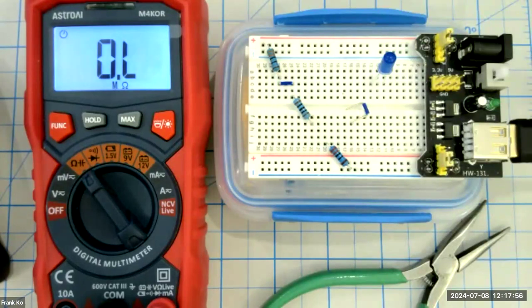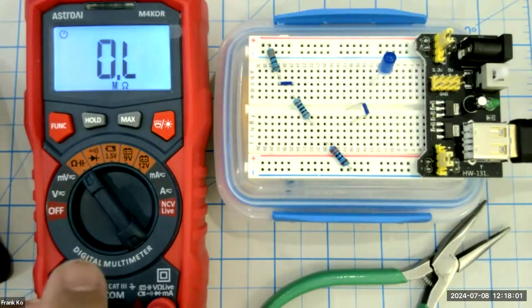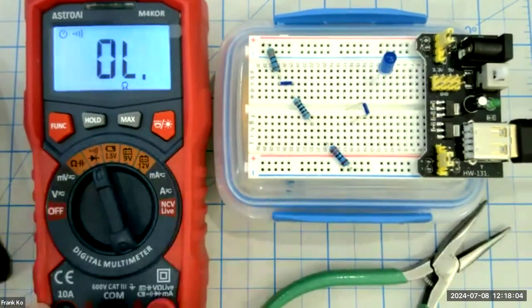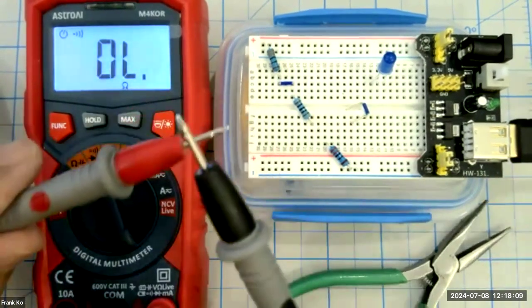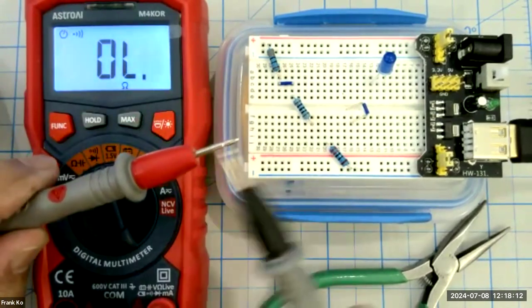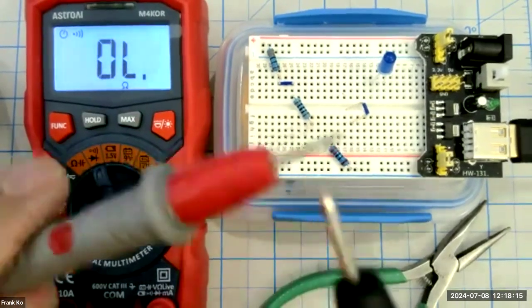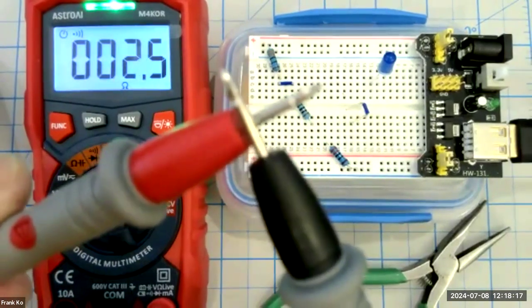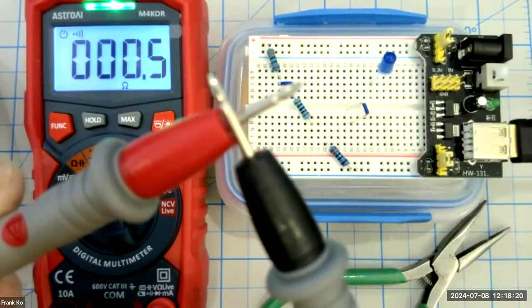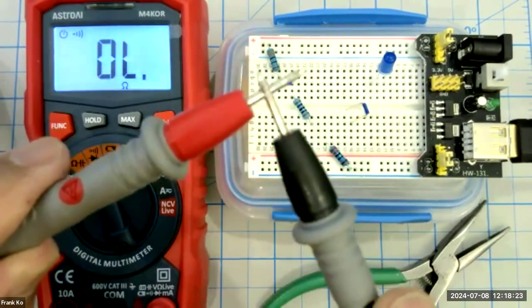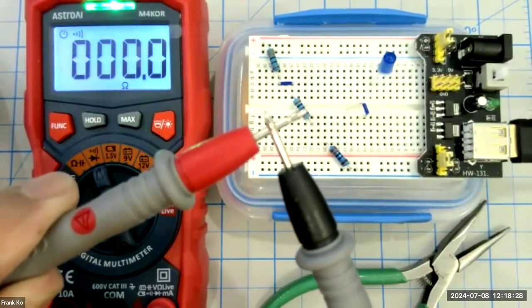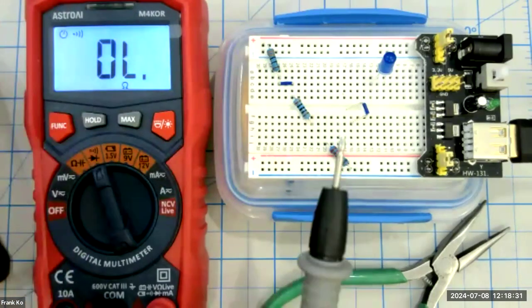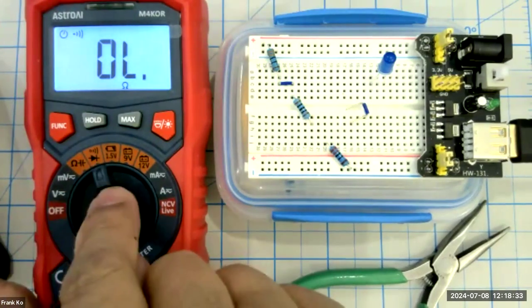Okay, and as I said, as a reminder from some of our first videos, to make sure your multimeter is working properly, we want to go to the continuity test mode, which is this position, shows a little sound symbol. Touch the two prongs together. We should see this change to almost 0 ohms. And if the microphone picks this up, you might even hear a beep. So it lights up, it goes to almost 0 ohms, like so. You may or may not hear the beep, but the green light says we've got continuity, or we're pretty close to 0 ohms. So the first thing you want to do is make sure your leads are working, multimeter is working properly.